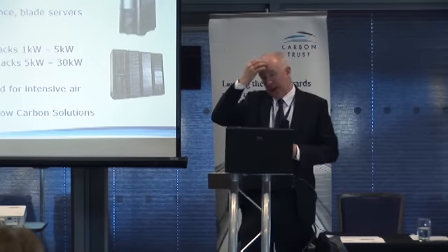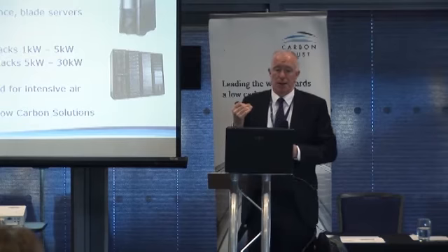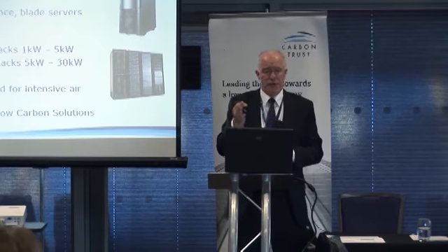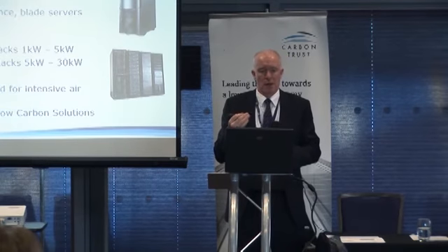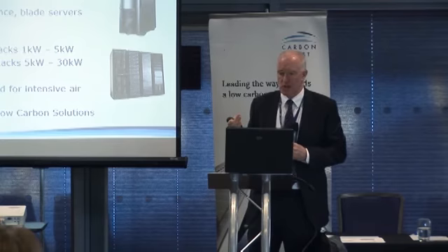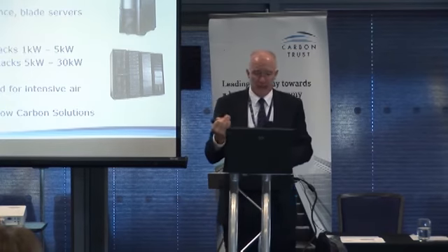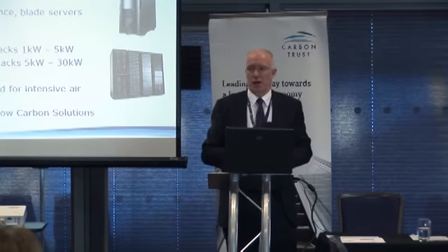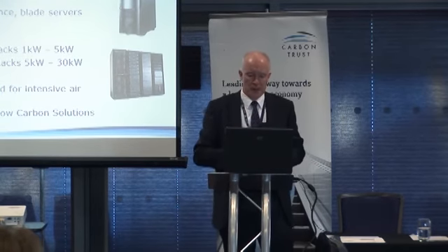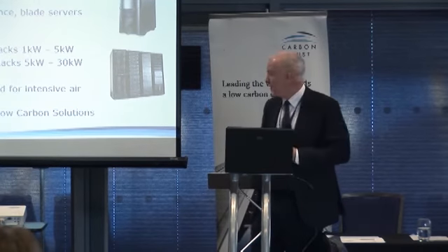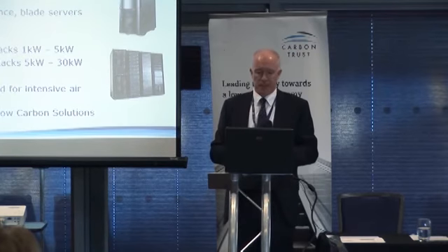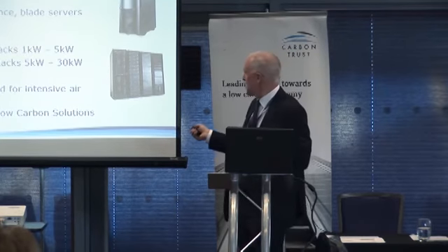In terms of the power demand within a computer centre, the individual electrical consumption of network servers is often around 100 to 200 watts. That's a standard amount. More recently, over the last 10 years or so, high-performance blade servers have a capacity for generating heat that can be much higher, up to 2 kilowatts per unit, something like that. And I think it's quite useful to have a look at what your rack densities are. So here again, you should be working with your IT staff, looking at the racks and what density of equipment we've got. What is the wattage of this equipment?